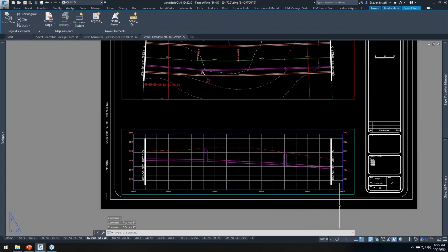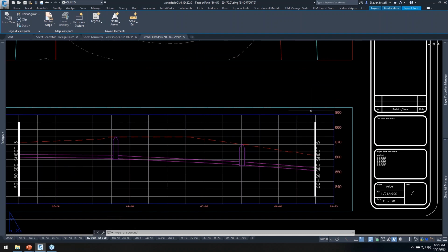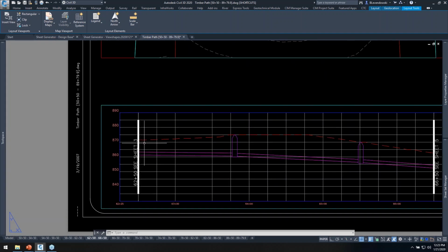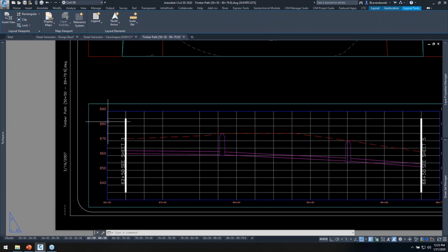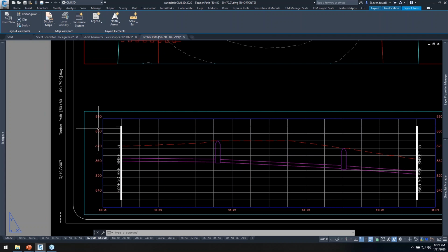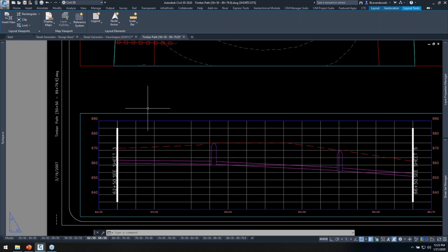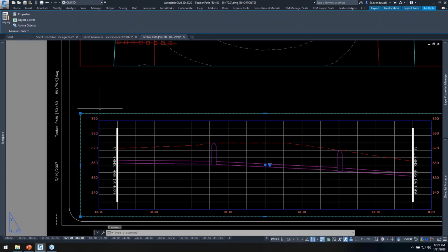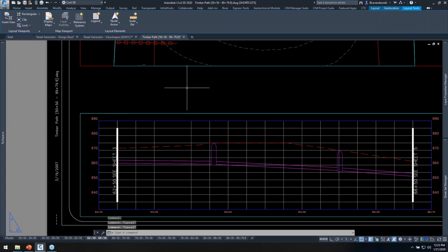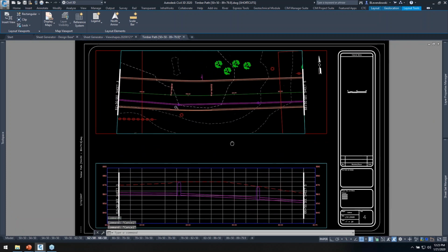And then down here in Profile View, I told it to do Profile View match lines. Okay, there's that extra grid spacing we said we wanted. Some of you might be thinking, well, I want my grid to go an additional 25 feet, or I want my numbering on the inside of the grid. Whatever you want to do, you can do it. You edit your profile view styles to look however you want. And then you adjust these blocks that you create for your sheet template, make those whatever size you want, and you can place your profile views however you want within them. And it'll be automated all with this tool.